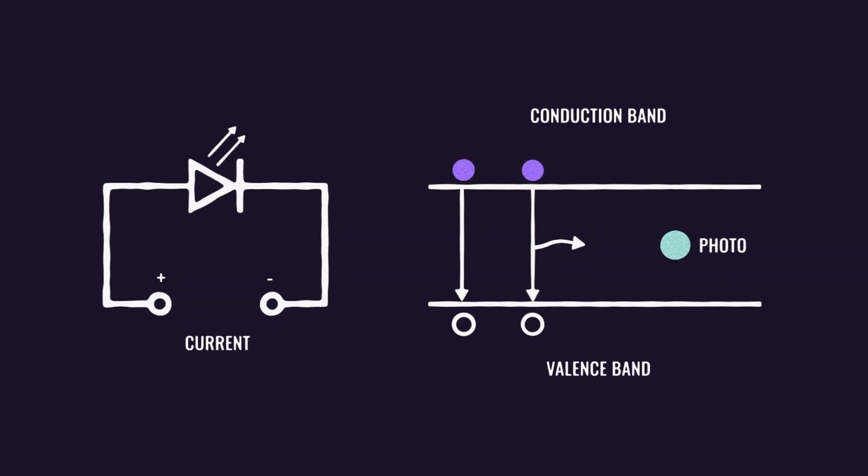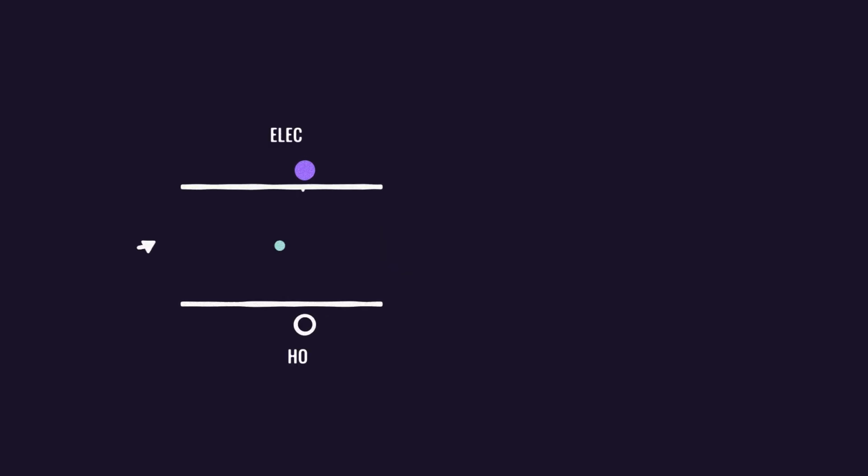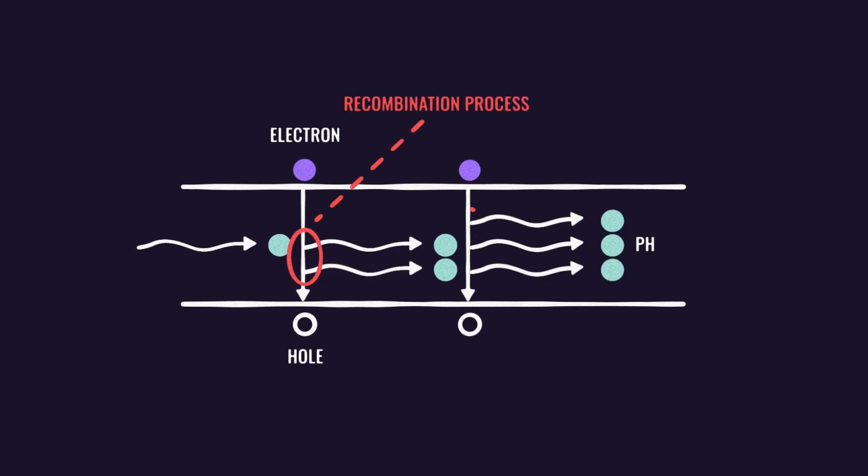Just like for LEDs, supplying lasers with electrical current allows lasers to produce light. However, lasers utilize a semiconductor phenomenon called internal optical amplification, which occurs when very high electrical current is pumped into a tiny laser. A single emitted photon in a laser can kickstart more recombination processes, producing yet more photons.